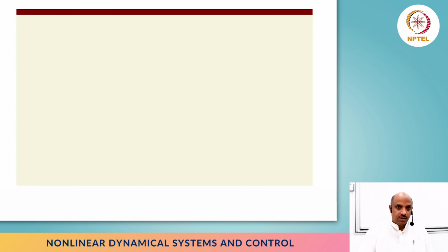Once we get the Lyapunov function locally, one can estimate a domain of attraction, and maximizing that estimate is a problem in itself. Typically in analysis, if we have a way of directly attacking the nonlinear system using some nonlinear Lyapunov function, that will be better, since we get global results or bigger domains of attraction.